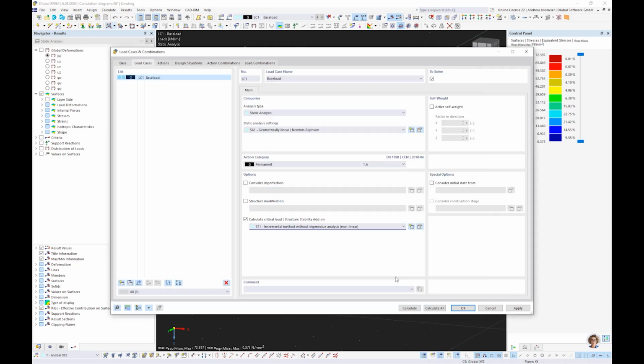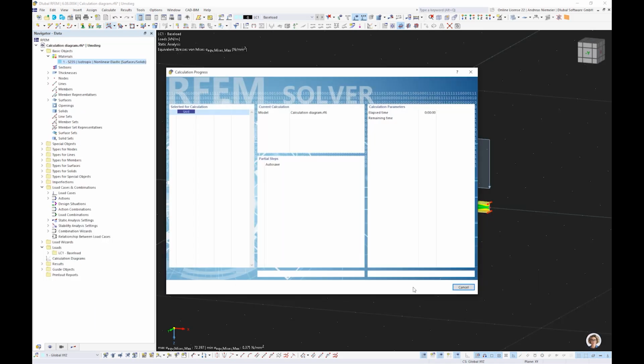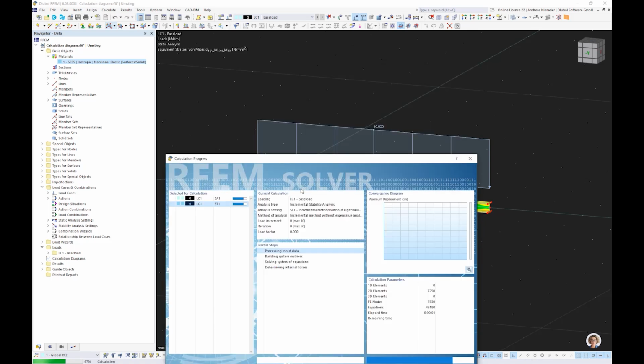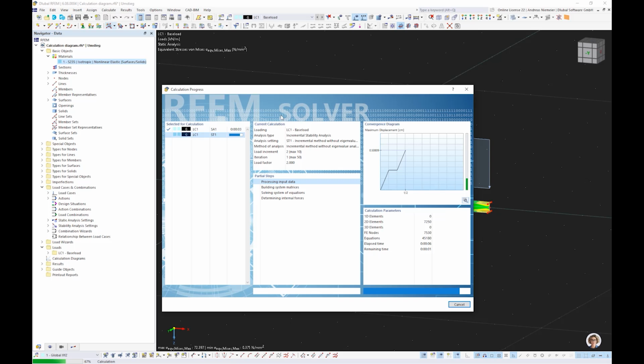And if we do this, the program has 2 steps: one for static analysis for the 10 kilonewton, of course, and another is the load increasing step. You see now how we increase the load stepwise. Now we slowly come into this yielding effect. Of course, we see only the diagram now, not more, not less, so we cannot decide what happens. But later we have to look into these results, and because we store every result separately, we have the chance.